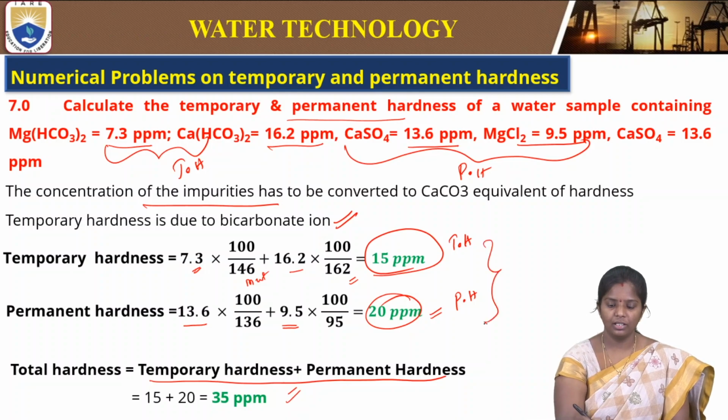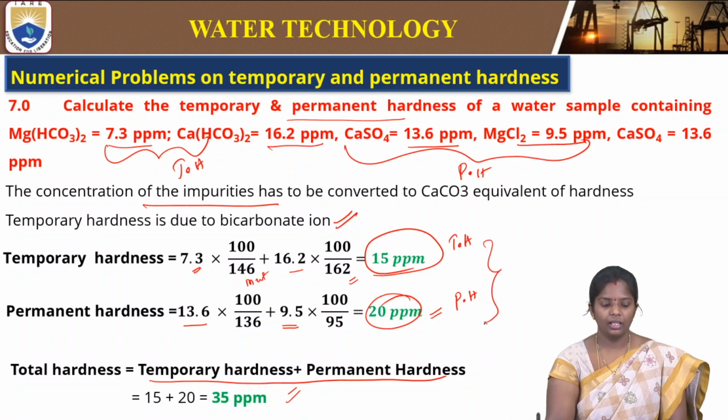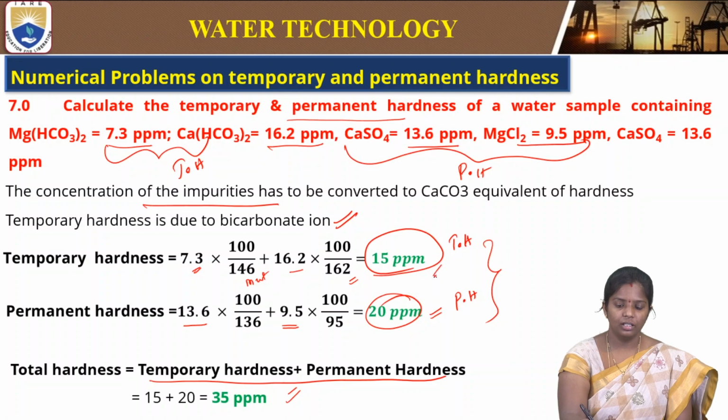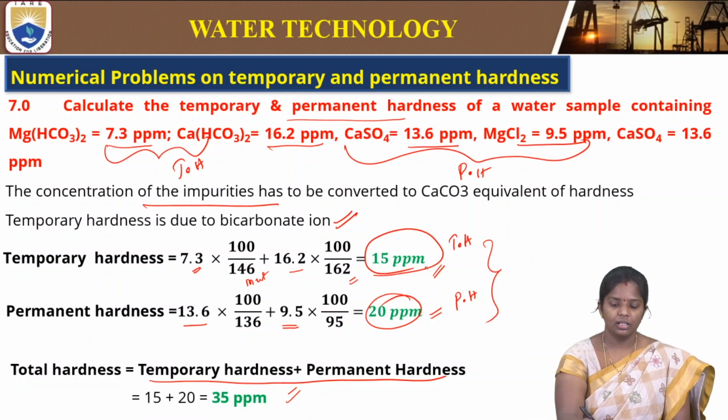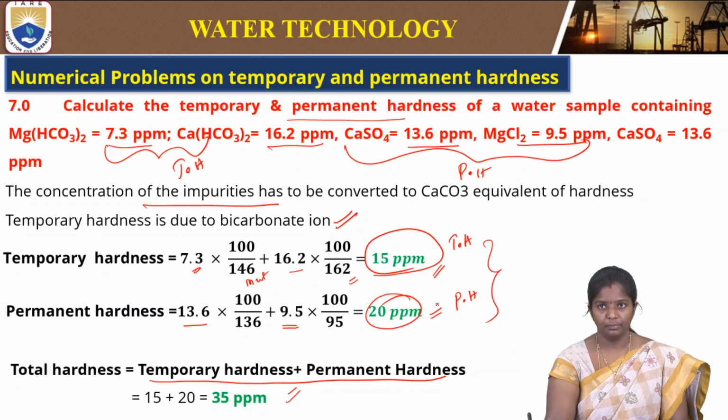If we compare these two values, similarly, slightly high chlorides and sulfates are present. Therefore, even the removal of temporary hardness is very necessary through boiling or any other treatment too, because it is present almost equally.